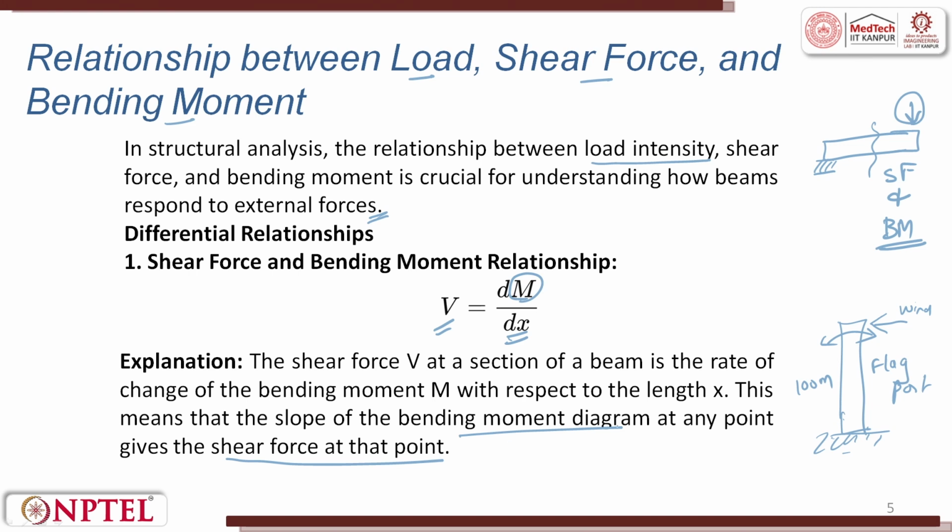Please note it down. This is very, very important. We will draw a bending moment diagram for every structure; that we will discuss in this lecture itself. When we get the slope of a bending moment diagram, we get the shear force at that point. That is why we represent shear force V = dM/dx, the rate of change of moment along the length.